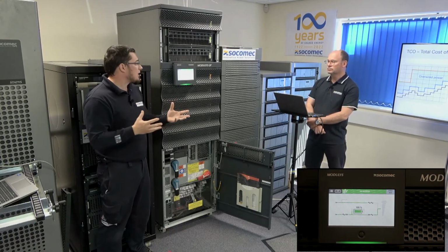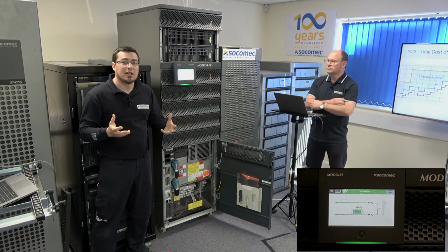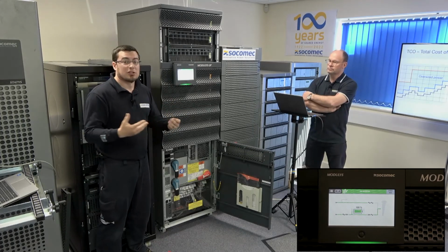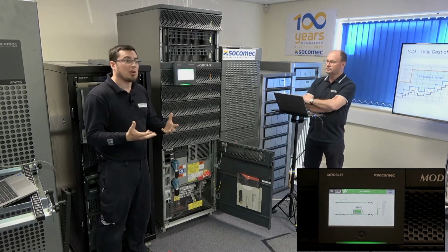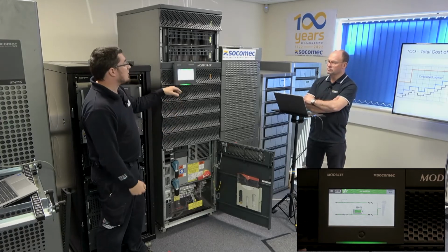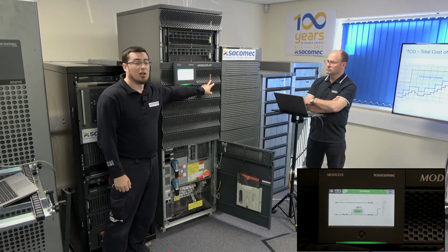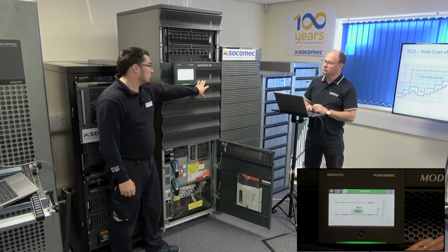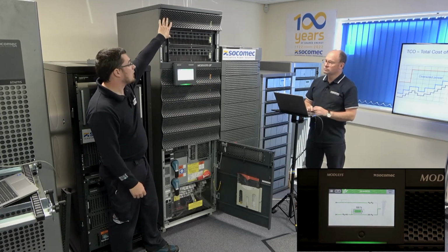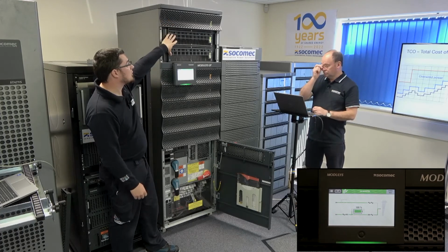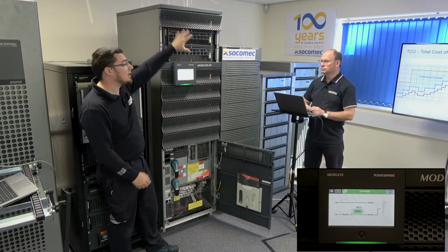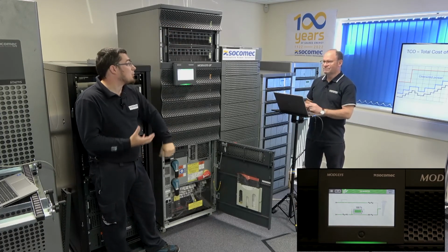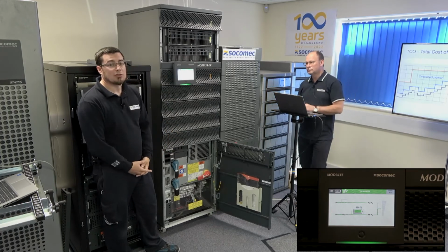And again, with energy saver, if any alarm event occurs, so if we go on to batteries and there's a mains failure, it switches all the modules on straight away. So as you can see, we put it into energy saver within a few seconds. The bottom module here has gone offline. So we've got two modules that are online for the system and one for redundancy. They're all on, they're all working, but it maintains that redundancy level based on what you've set and the applicable load at the time.